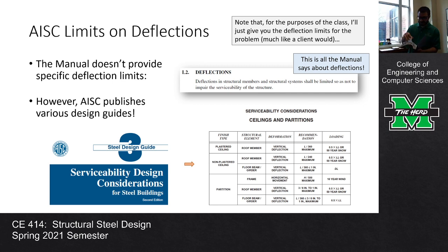But if I open up the spec and I go to the section on serviceability, which is, I think, in this section, 126, right here, the spec does a really good job of listing permissible deflections. They're right here. It says maximum permissible deflections for a beam. The ACI spec does a really good job of delineating to the engineer.